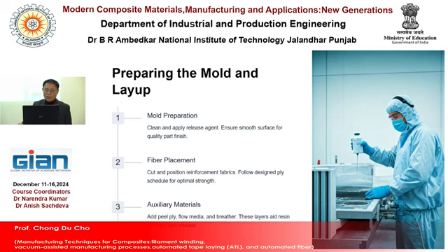Then auxiliary materials are needed: peel ply, flow media, and breather. Those sheets should be placed over the preform to help the resin flow.